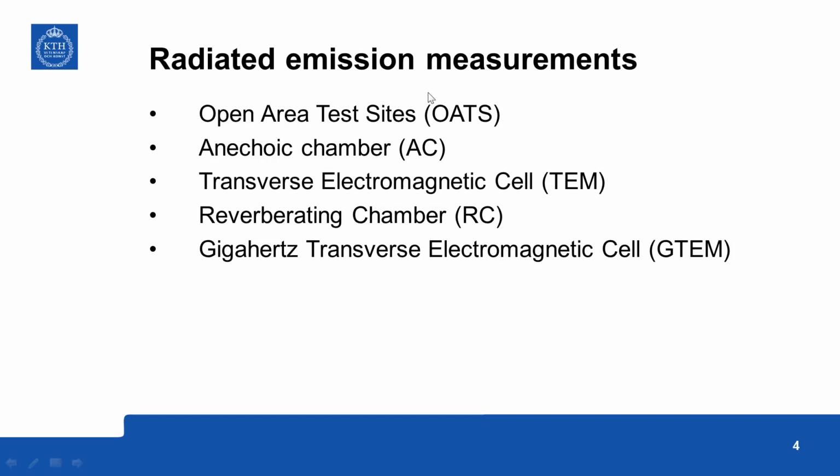So, radiated emission measurements. Some of the techniques used are open area test sites. This is more like a reference test system. Anechoic chamber, transverse electromagnetic cell or TEM cell, reverberating chamber, and Gigahertz transverse electromagnetic cell.